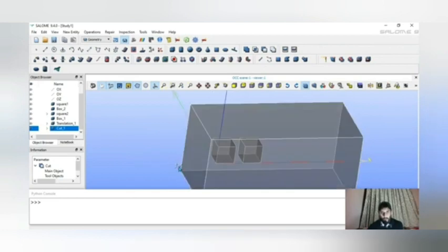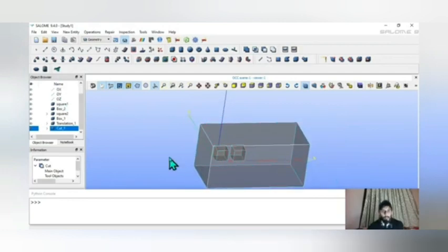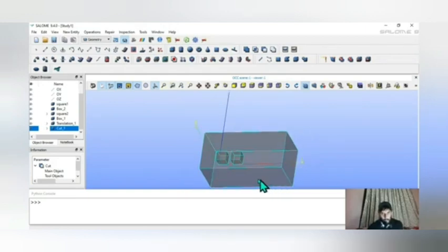So we are not having 3 entities here, the external box and then 2 squares inside. No, this is just one entity. Why? Because those squares have been cut off from the bounding box, right? So now we need to put these 2 squares into separate entities. Why do we want to do that? Because we want to have full control over our squares, because that's where the mesh is going to be concentrating more, right? For example, if you're having a wing section, or maybe a subdivision of the wing section as a tail fin, you would want to have full control. So in order to get the control, you need to put them in a group.